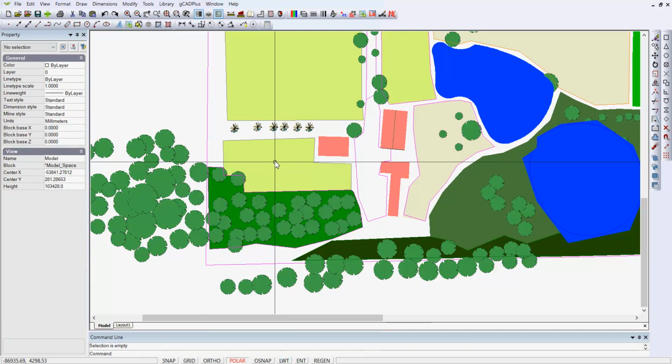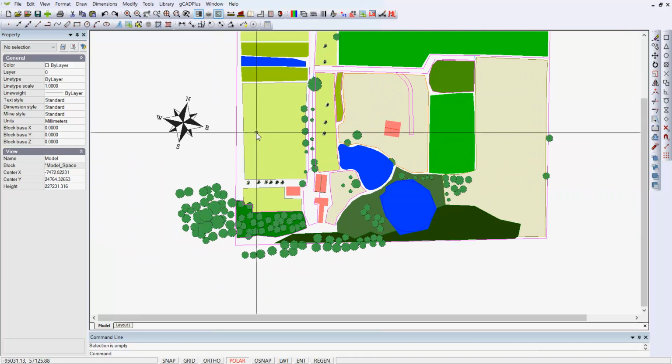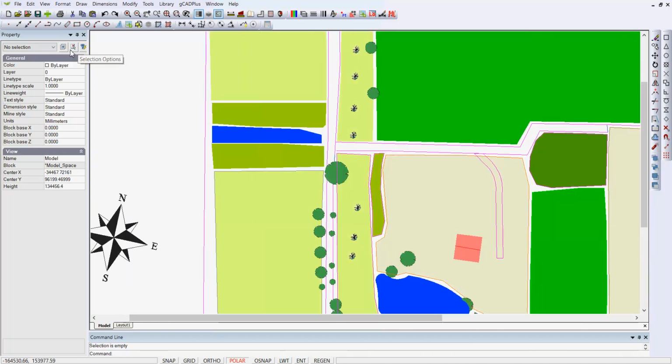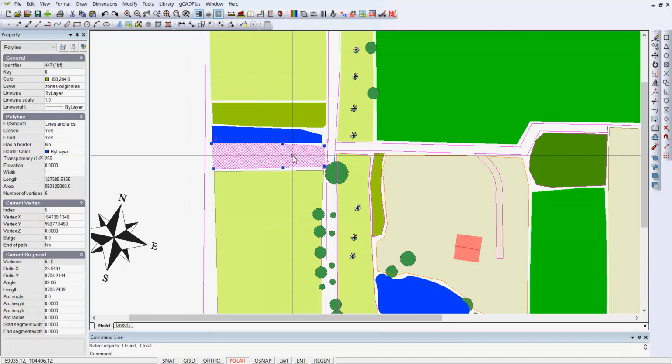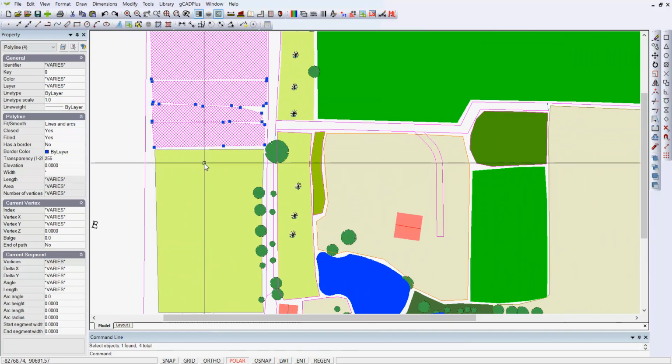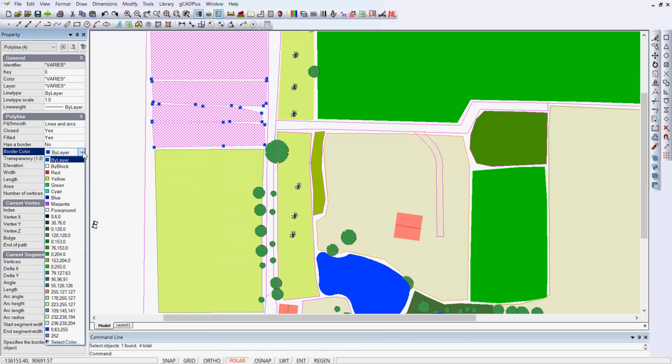Can you see now it's just one entity still? It's just 1 polyline, whereas we had a hatch and 2 polylines superimposed on one another. Now we've just got the 1. So I think it's a lot simpler. So if you did need an outline, you now can see a simple way to do it. And because we've changed this to a plus sign, we can pick all of those zones, which are now indicated by a polyline. We can say to all of them, they have now